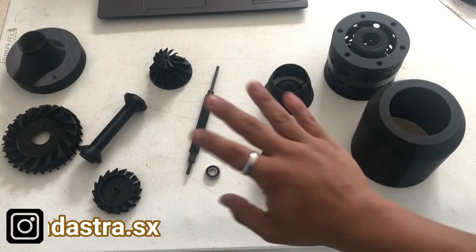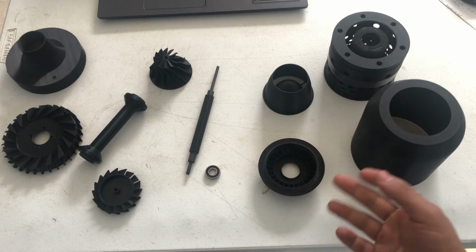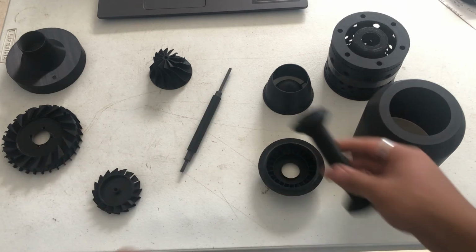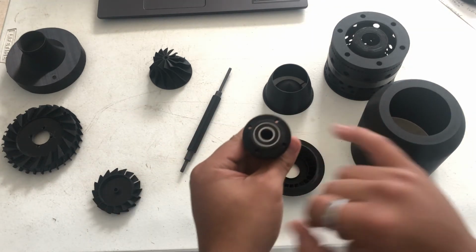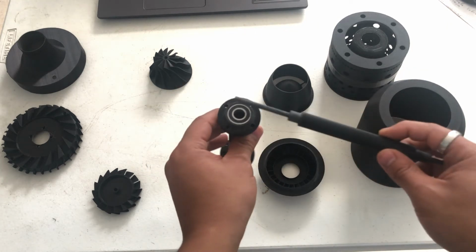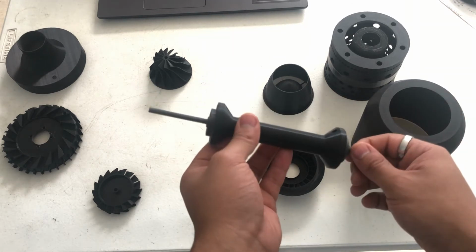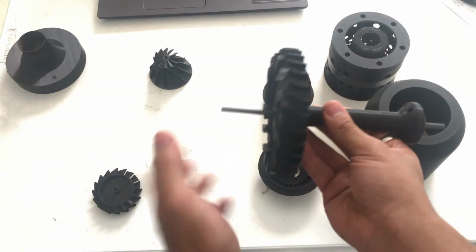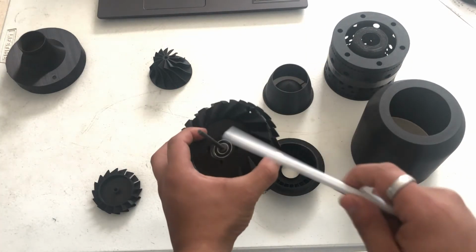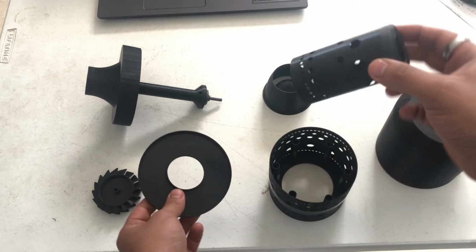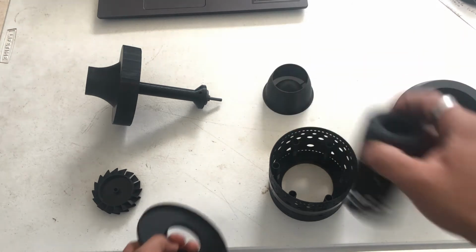If you want to make your parts on a lathe or a CNC, you must know how to assemble the pieces, so let's proceed. Buy two 21mm bearings, place one here, put the shaft inside the shaft housing, and leave the remaining bearing until the end. Now proceed to connect the diffuser with the shaft. You can go ahead with the compressor or with the combustion chamber. The combustion chamber is composed of three pieces: the base, the internal wall, and the external wall, which has the cylinders.